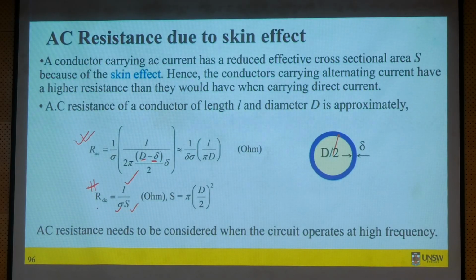Yesterday I mentioned hairpin winding, right? So usually AC resistance in the conventional wire you minimize by using very small cross-sectional area wires, and then use several of them to make one single branch. If you take out any motor and look at its cable, you will see that there are many small branches tied together to give you one single conductor. So its reason is actually this, to minimize AC resistance.